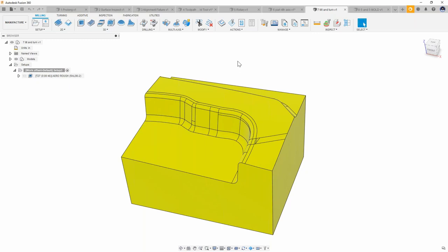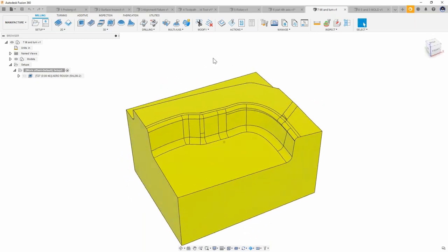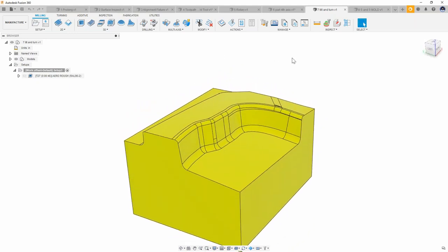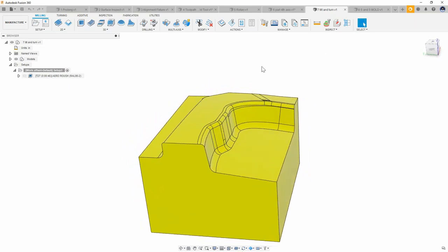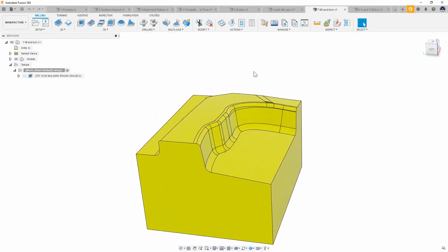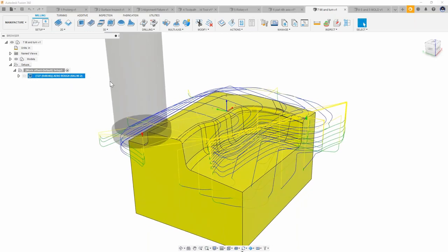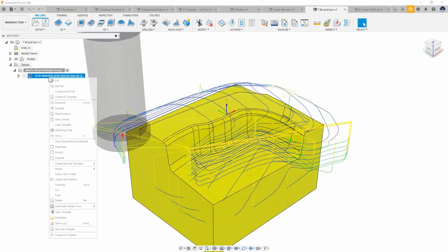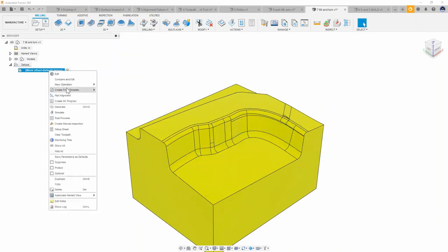And generally with 5-axis or even systems in general, when we're looking at doing planes or machining operations in a 5-axis and a 3+2 machine, we want to make different planes or frames or different vectors. And in a lot of systems, that work is required to generate a toolpath. In Fusion, it's not. So I've already created a roughing operation here, so we can just focus on the finishing. But even for those new to this, maybe this would have been beneficial. I'll delete that. Sometimes I make mistakes.